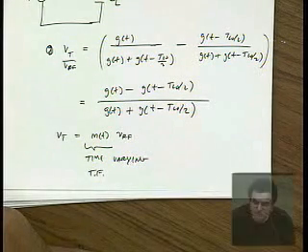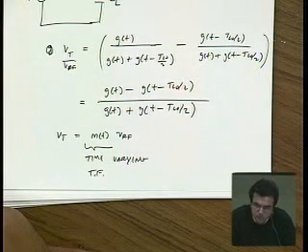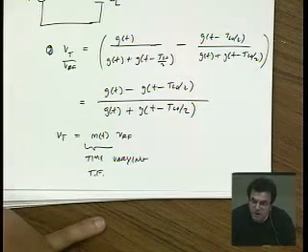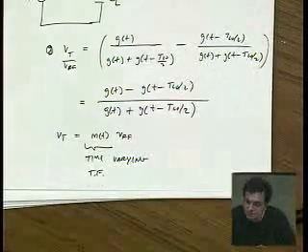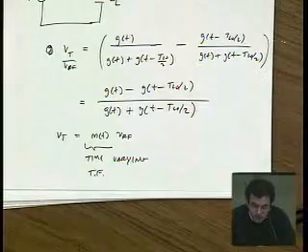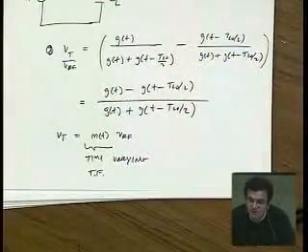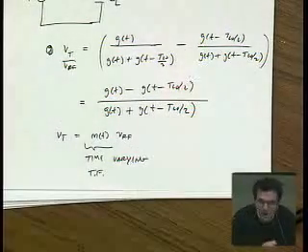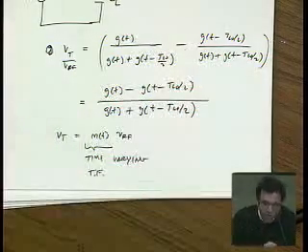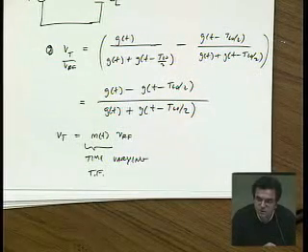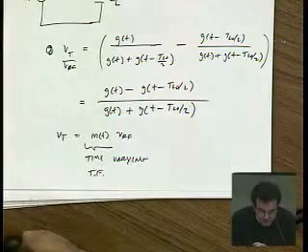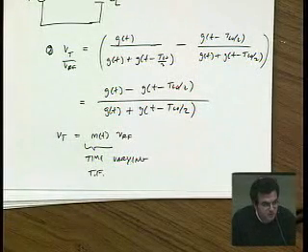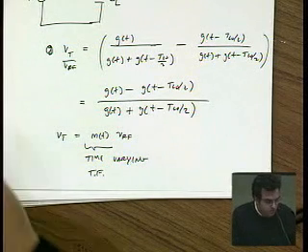Yes? Two matching questions. One is how critical the matching between L1 and L2 in the circuit. Number two is how critical the timing for the pi over 2, or pi, I guess. Yeah, they're actually both important. All the good properties of the mixer come about if you assume perfect matching, right? If you have perfect matching, you can reject the LO port noise, for instance. If you have any kind of jitter in the clocks, any kind of mismatch in the clocks, then you will not have the good properties that the waveform has 0 DC value, that the waveform is half-wave periodic, symmetric. So all these good properties which lead to good performance depend exactly on having good matching, good waveforms. So it's very critical when you design these kinds of mixers to drive it with 50% duty cycle LO, be very careful that all the paths are matched, and so on and so forth. Okay? Any other questions?